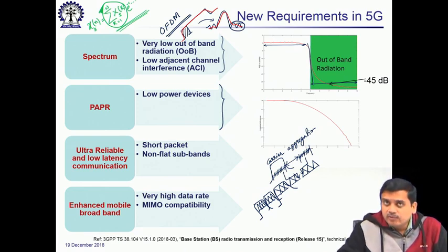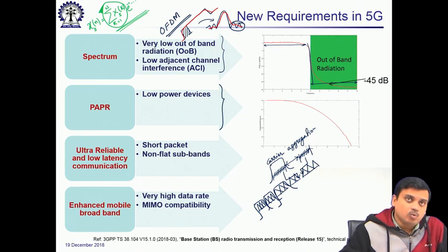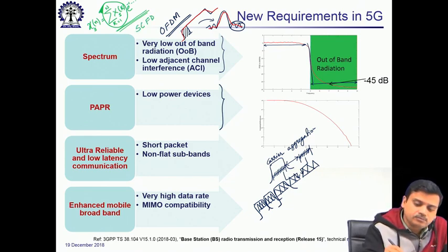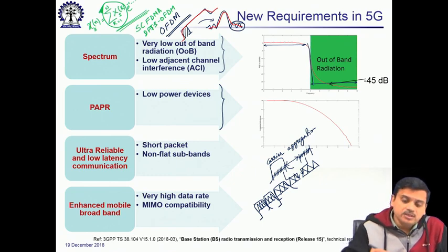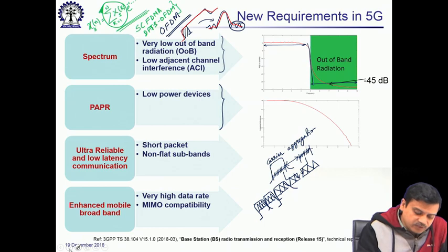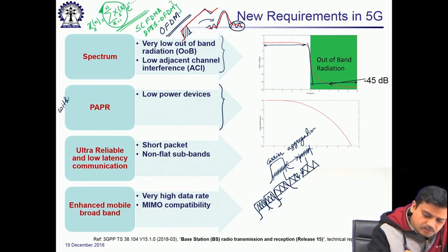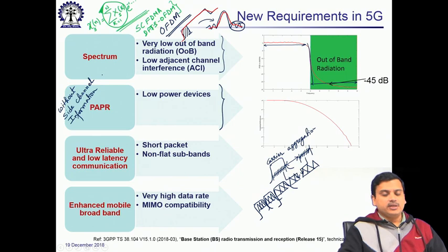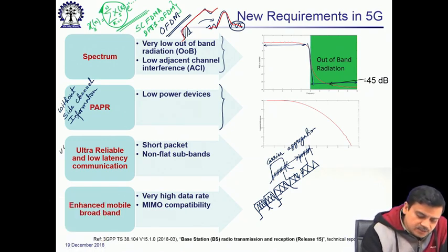So, what it says is that if we can have low PAPR and yet have multi-carrier, then things would be wonderful. So, this is the kind of requirement, and we will see some solutions which do really provide some great advantage. One of them we have already seen, that is SC-FDMA, which is nothing but DFT spread OFDM, and hence there is already a mechanism by which things can be reduced. There could be other mechanisms also, and all these without any additional information being sent over the channel. So, what is very, very critical, without side channel information, that is also important. Because if you are sending side channel information, there is a huge increase in extra bandwidth, or in other words reduction in spectral efficiency.